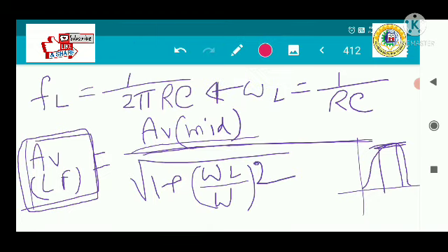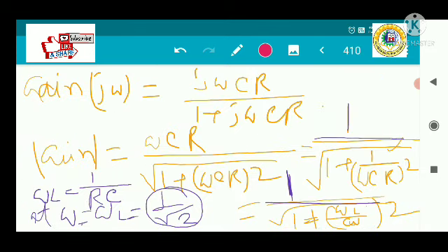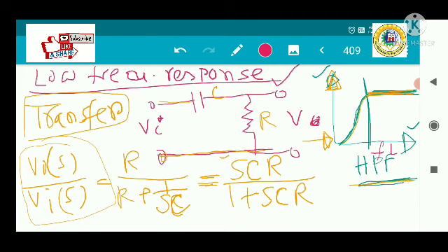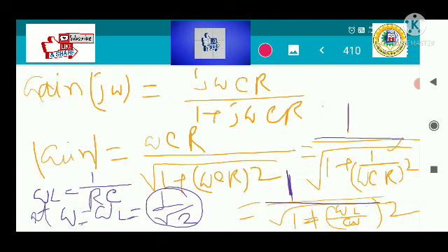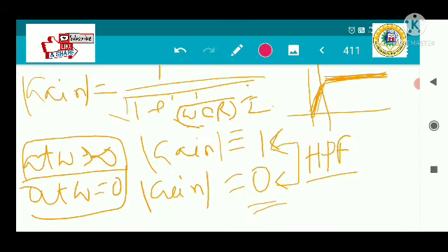So whenever we analyze the transistor at the low frequency and try to analyze the cutoff frequency, then we must use this equation. I will advise you to pay attention to this: the low frequency response of the BJT looks like the high pass filter. That's why we have studied the passive high pass filter circuit analysis and try to compare it with the BJT.